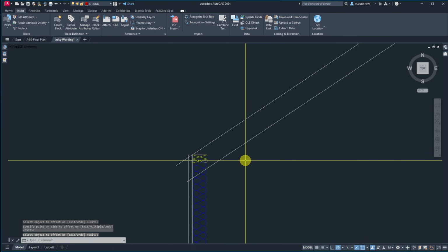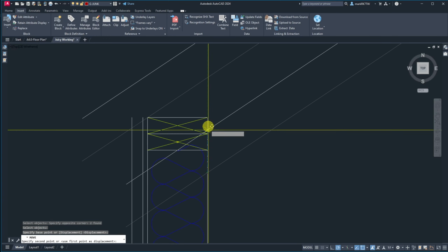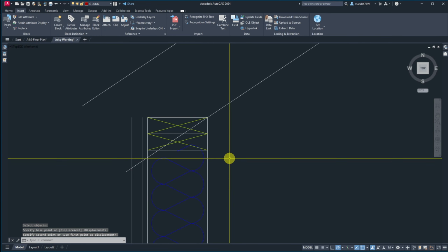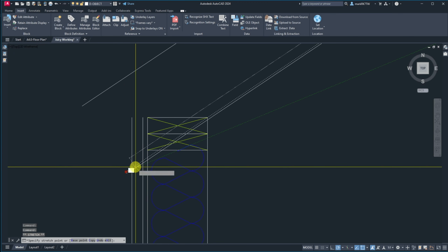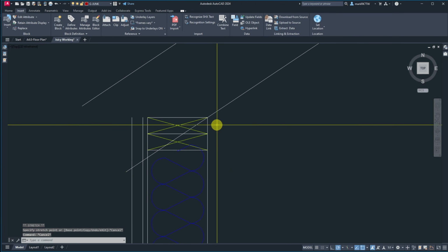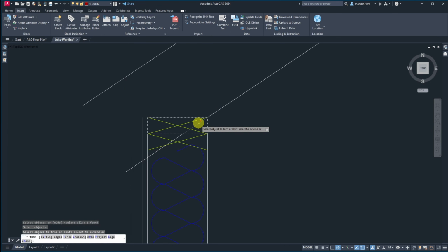And actually what just happened is fine, because if it is truly stick framed, then I'm going to have a bird's mouth cut. So I'm going to take this and pull it back. Or, it's better than pulling back, let's trim it between here. Oh, that's good enough right there.